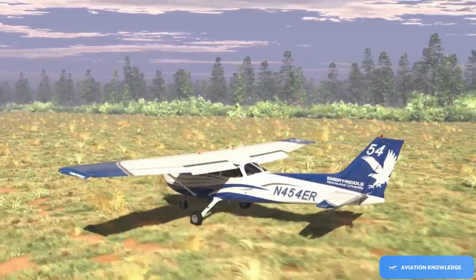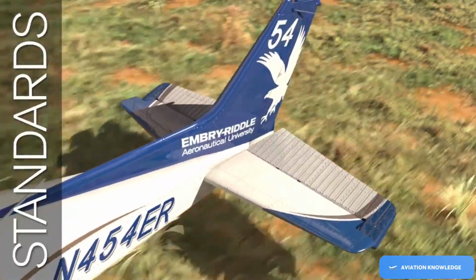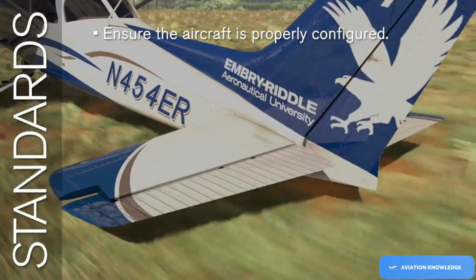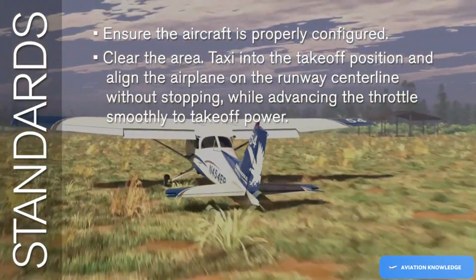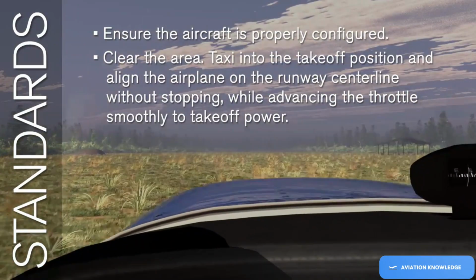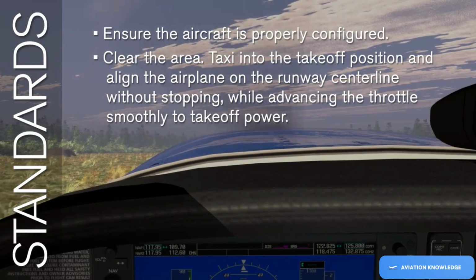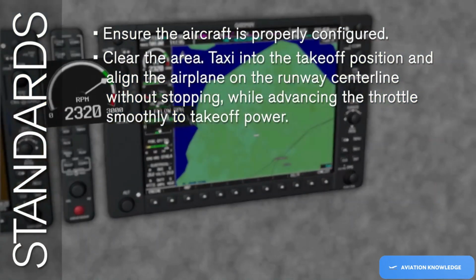Now that we've covered how to fly the maneuver, let's look at the end goals for your skills in a soft field takeoff. Some of the standards for the end-of-course check ride include: ensure the aircraft is properly configured. Clear the area, taxi into takeoff position, and align the airplane on the runway centerline without stopping while advancing the throttle smoothly to takeoff power.